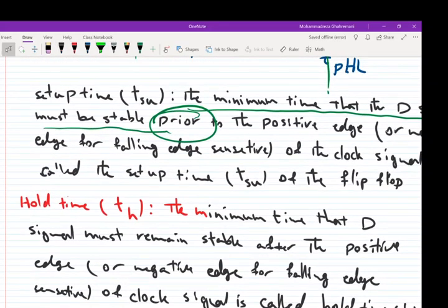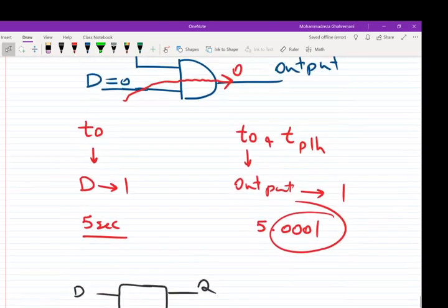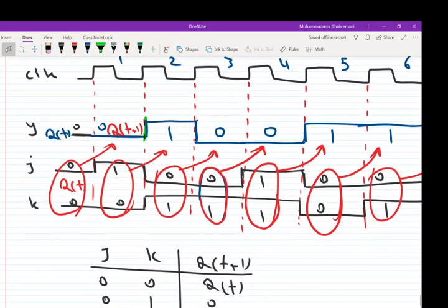So the next time I give you an example like this with the flip-flop and ask you to complete it, I don't want you to show the signals like this. That's okay if you do that. That's fine. But the one thing you are supposed to show is the propagation delay. So the Y output, I want you to show the Y output like this.